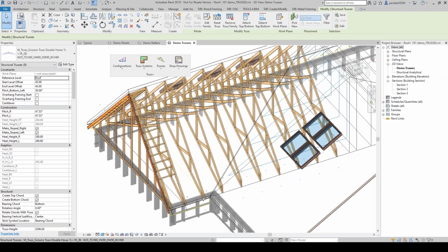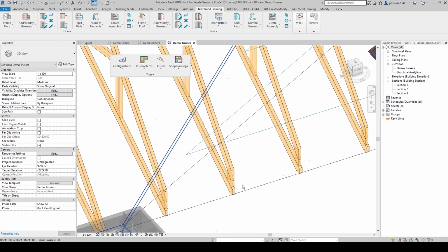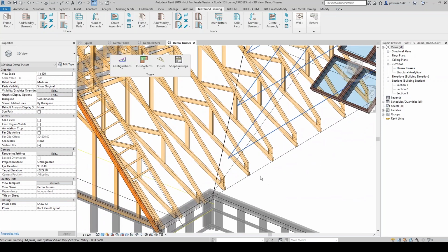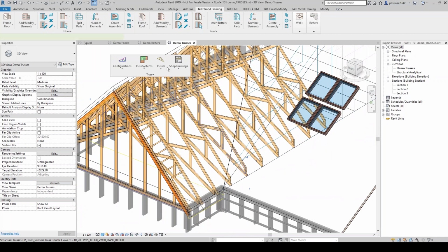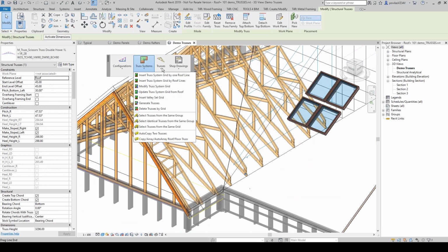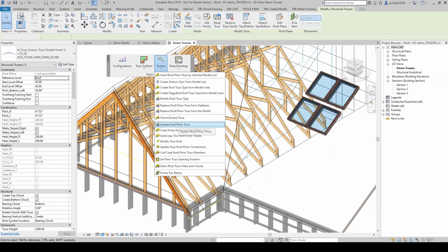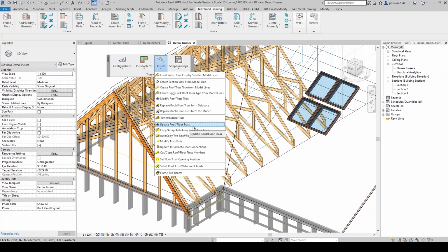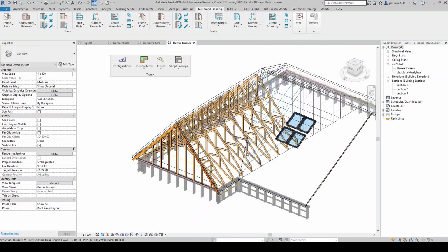So because that side of the truss no longer is facing the external surface of the roof, the end cuts would need to adapt to the new location. So if you just select the truss like I did and update according to the roof geometry. Okay, so right.